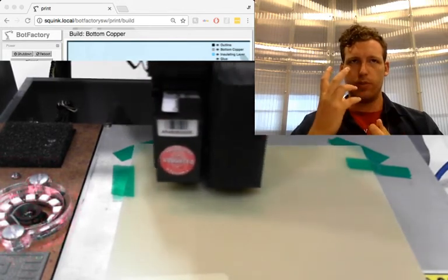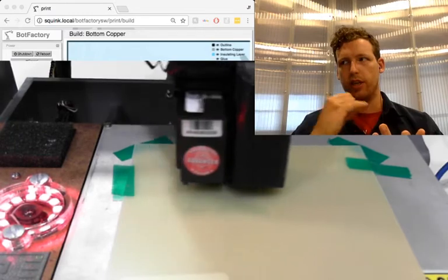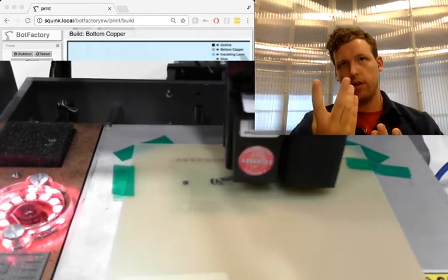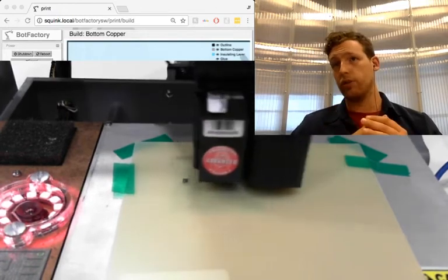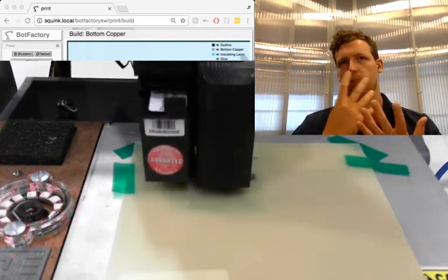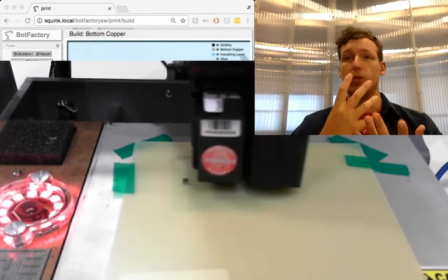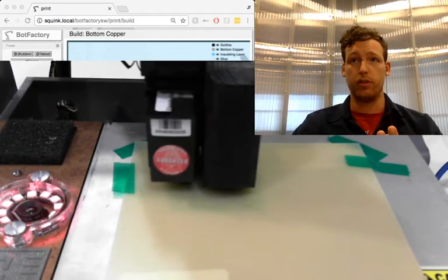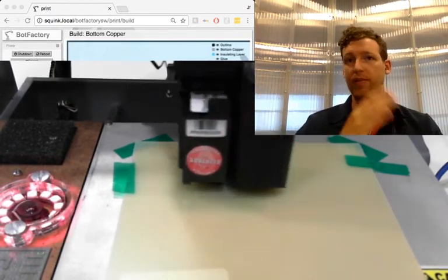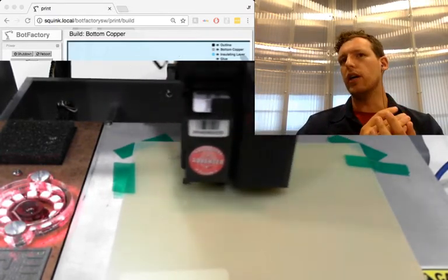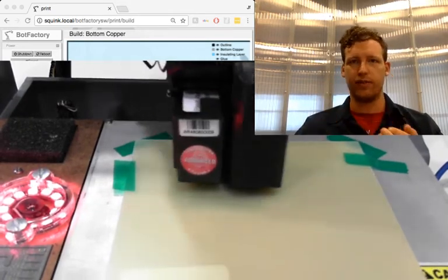When the particles hit the substrate, the heat essentially causes the carrier fluid to evaporate, and nanoparticle silver, like most nanoparticle metals, has an interesting property whereby it melts at a lower temperature. So we were actively melting silver, whose melting temperature I believe is above 1,000 Celsius, at a tenth or less of the required melting temperature for bulk silver.